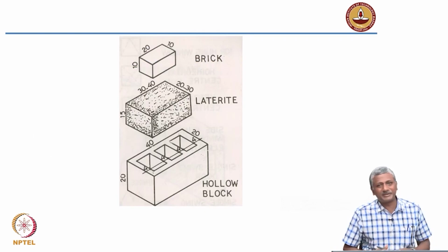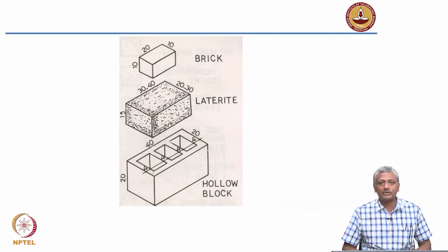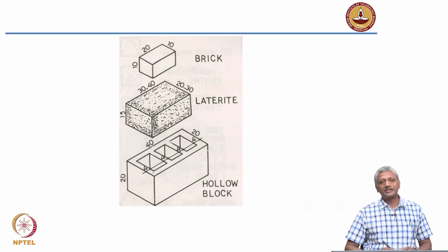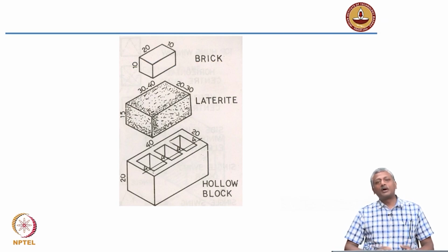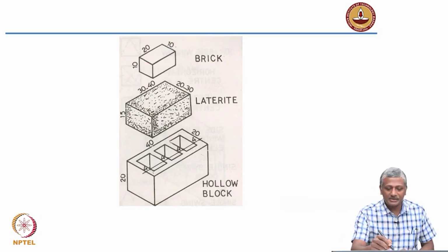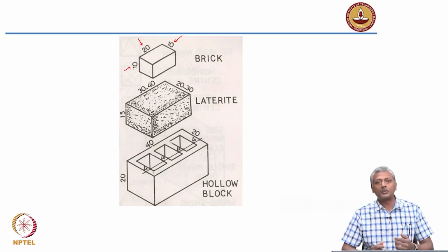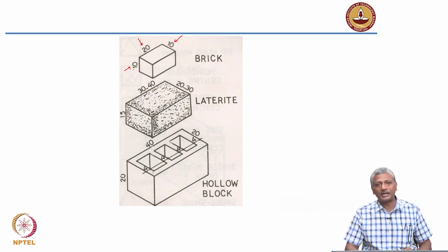Now, just to give you some examples of typical sizes, you may have seen these stones and bricks lying around on job sites. Some of you may have lifted these also, but if I ask you the weight of a brick, many of you would probably think that it's about a few hundred grams, okay? But you don't realize that with this size, this is a typical modular size of a brick, 10 centimeters by 20 centimeters by 10 centimeters. This is a modular size. This is what we use for design and drawing purposes, but the true size is quite different. I'll talk about that a little bit later.